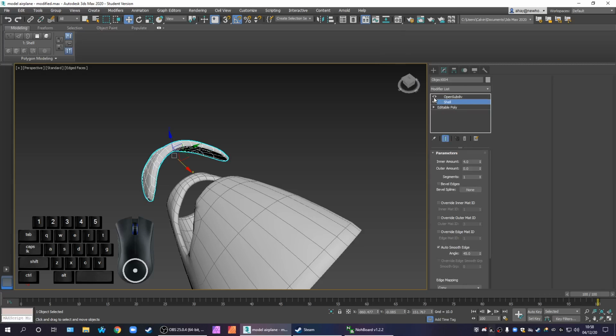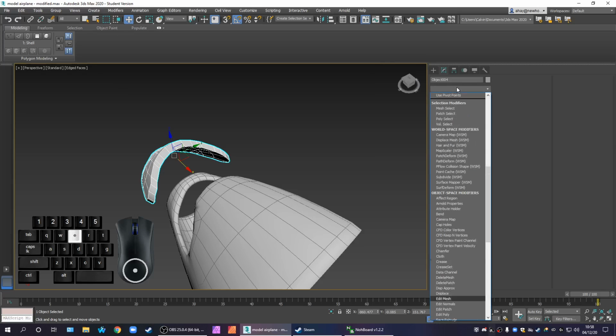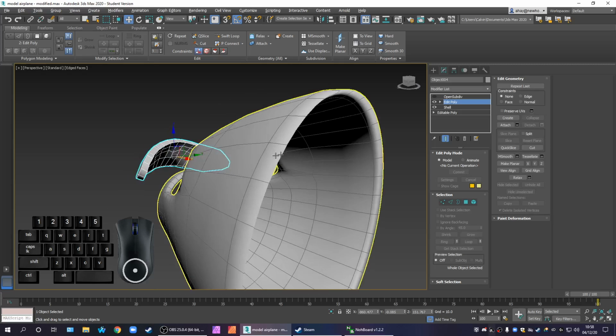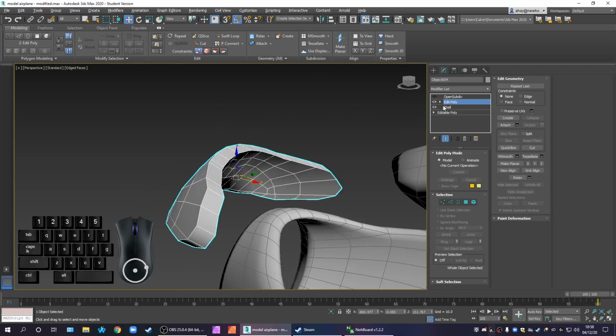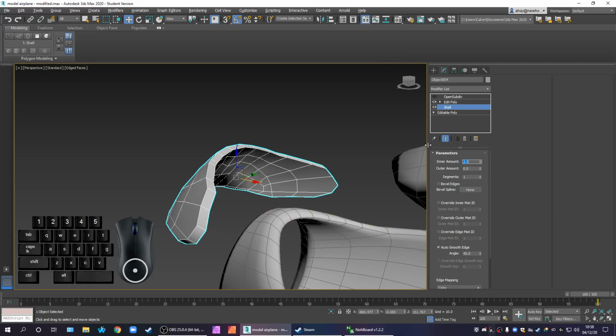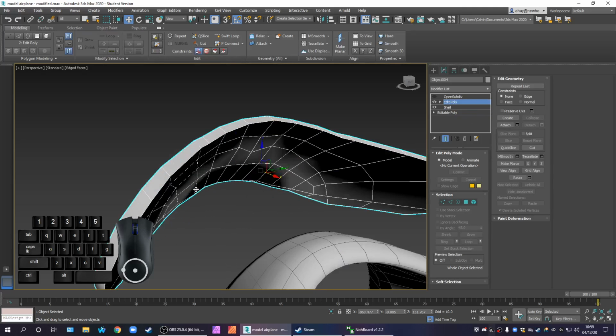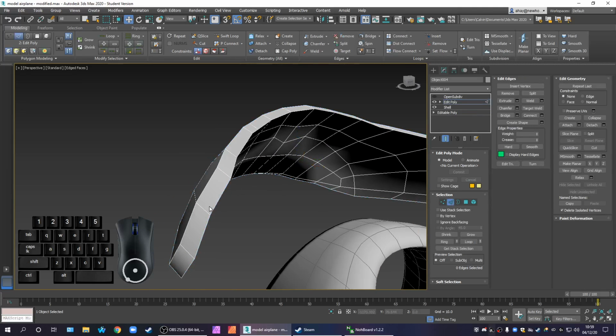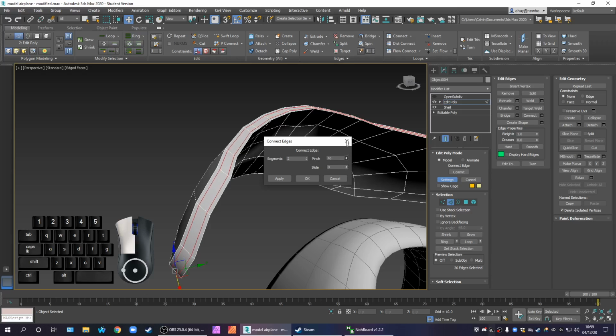So after our shell, but before our open subdiv, we ought to do edit poly. And you know, the window can be a little less thick than the rest of it, right? Should do like 2. We'll ring, and we will do a connect just to harden this off. But I want to avoid hardening that corner, that was too harsh. This will actually help it hold.